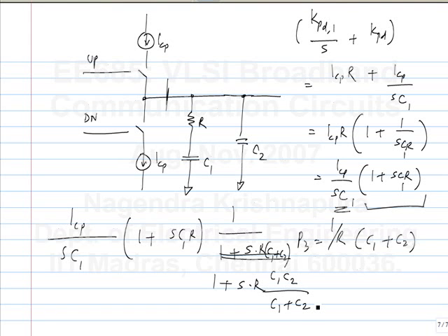What is the transfer function at very low frequencies of this? If you input a DC current to the system, what is the rate of the ramp? Should say C1. Why only C1? The current will flow into C1 plus C2, right? So the rate of the ramp is? Previously it was flowing into C1. So this is the ramp that you see at low frequencies, and that has changed. Is this clear?